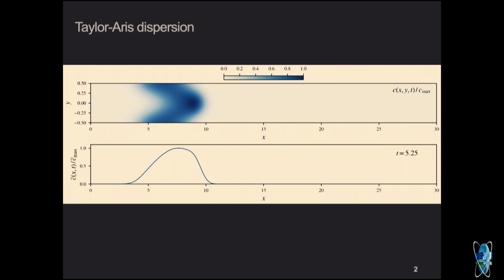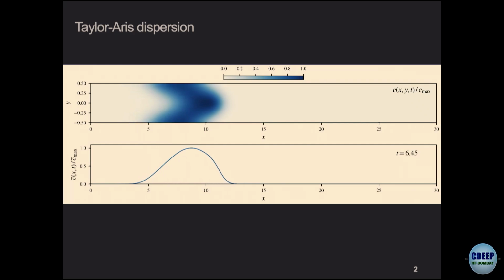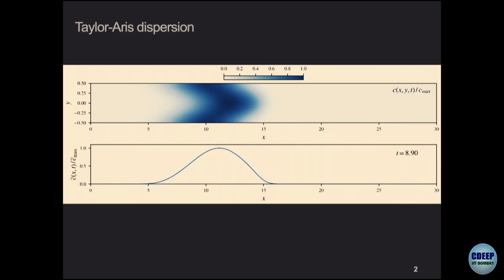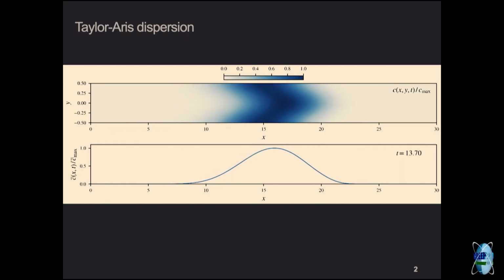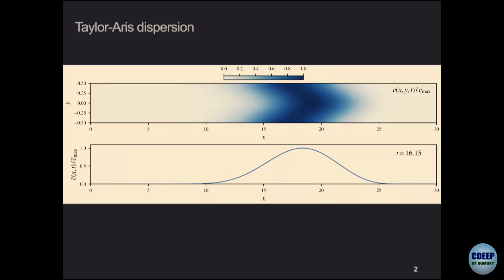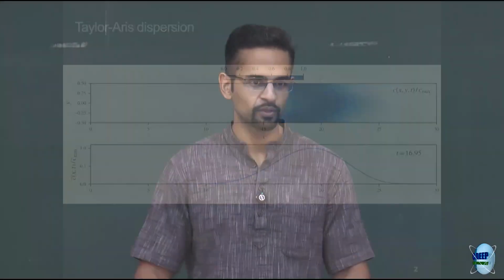So definitely, and this we can of course do from the experiment itself, if you just look at this concentration profile, which is easy to do in an experiment, you put a pulse, you stand at the outlet and you measure the concentration coming out, you will get a Gaussian profile at some distance. You change the flow rate, that will be as good as decreasing the distance. Reduce the flow rate, that will be like going to a larger distance. Or you can make pipes of different length. And you keep measuring this Gaussian, so you can see how the Gaussian spreads along the length, or in time.